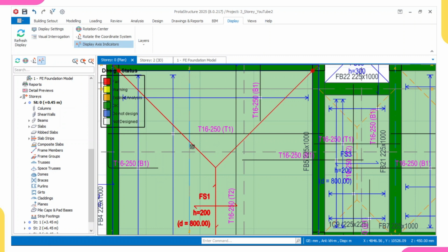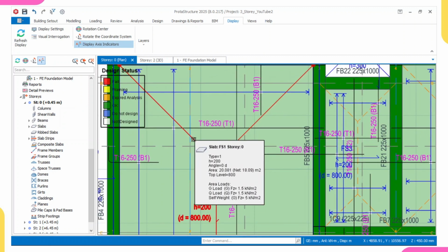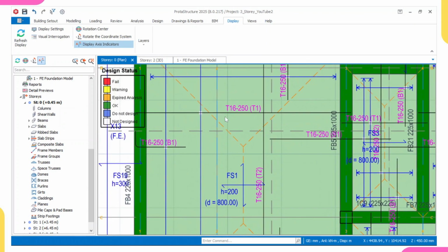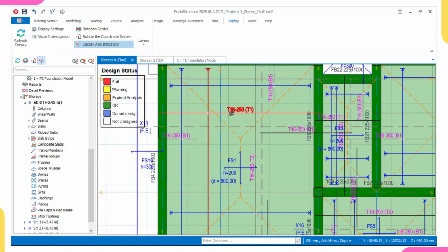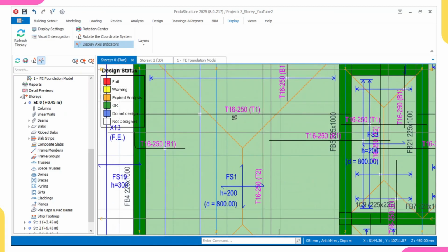I'm located in one of the African countries, which is Nigeria. Once it comes to most of these African countries, they tamper with quality. Yes, their T16 is not T16. Their T16 can be T13, T14, or T15, and thereabout. And the 460 yield strength that we use might be 430, 440, or thereabout. Because they are trying to make profits in their production. So for that reason, I'll try to counter that to prevent building collapse.